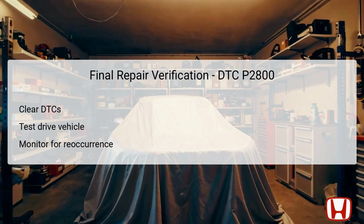Once repairs are made for the issues arising from DTC P2800, it's crucial to implement a final verification process. Begin by clearing the Diagnostic Trouble Codes, DTCs, from the vehicle's memory using a diagnostic scanner. This step ensures a clean slate for further diagnostics and testing. After clearing the codes, perform a test drive to assess the vehicle's overall operation, particularly focusing on the transmission's performance while shifting into reverse and other gears.